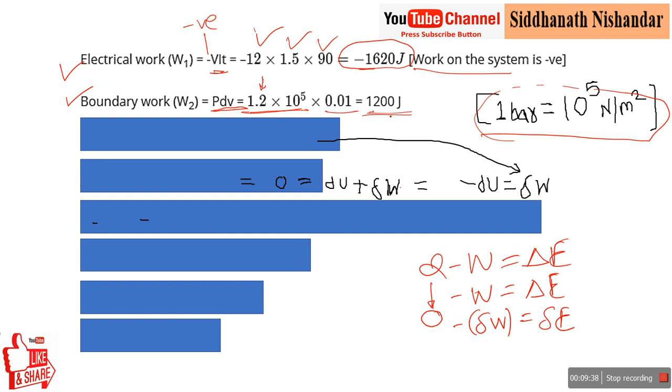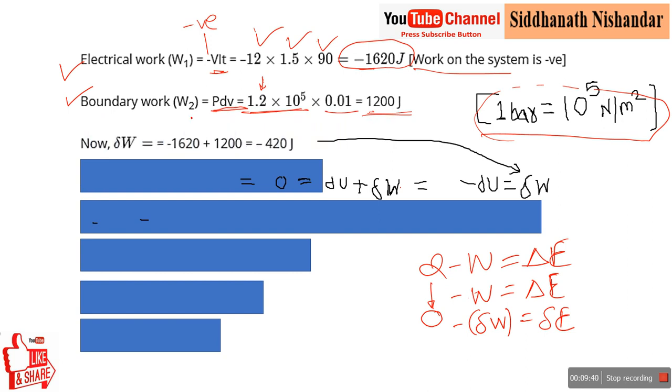So now the net change. This is work done by the system, so it is positive. The net change is what amount of work is supplied and what amount of work we get. Supplied work is negative, work obtained is positive. So the net change is minus 420 joule. There is some amount of work lost. We observe here around 400 joule of work is lost because that work is utilized to overcome the friction between the piston and cylinder. So minus 400 joules are utilized to overcome the friction.